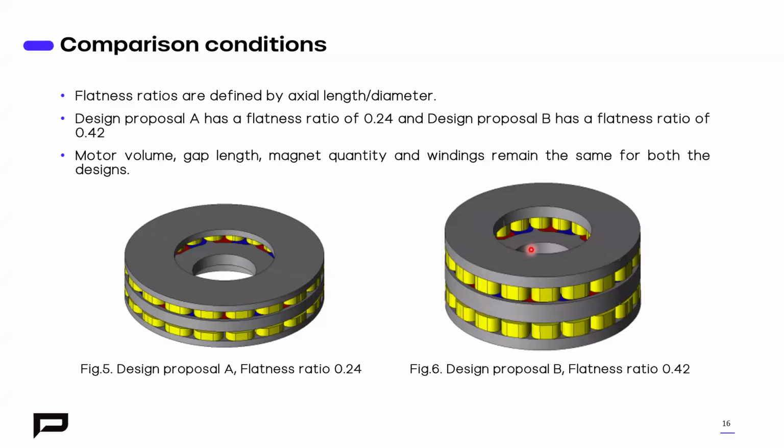And how does the software evaluate PM losses? Can we link SolidWorks directly to JMAG to create parametric geometry? Yes, you can take the DXF file from SolidWorks, which is your model, and you can directly import it into JMAG Designer.